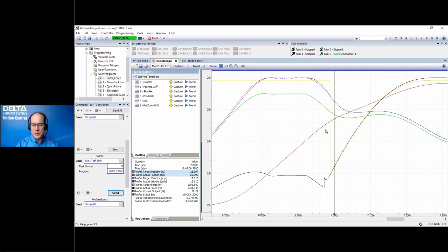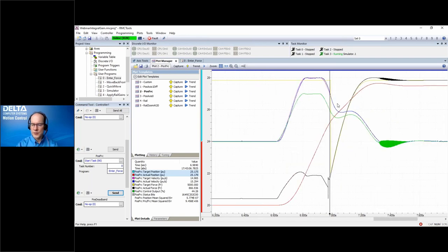Now, you could also argue that the force rate feed forward, or the force feed forward, is probably not set correctly, and that's entirely true. So you can fix it either by changing the force feed forward, so it will calculate on its own a correct control output, or you can stick it in the integrator preload parameter. The integrator preload parameter will probably cause a little overshoot. Look at that. Sure enough, we got some overshoot here. So it's not the best solution, especially if you have to have such a high value as 37. If it was down at 1, 2, 3, 5%, then we'd probably hardly see any overshoot at all.